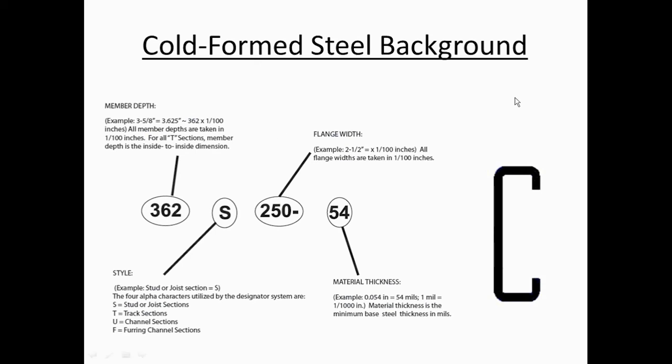If I have load applied coming down from above, like this cursor is showing, on this flange, this profile is put in what's called bending, where the top flange is in compression and the bottom flange is in tension. They are the primary structural elements in resisting that bending, what's called a moment. The web, which is this element here, is doing nothing more than keeping these two separated.